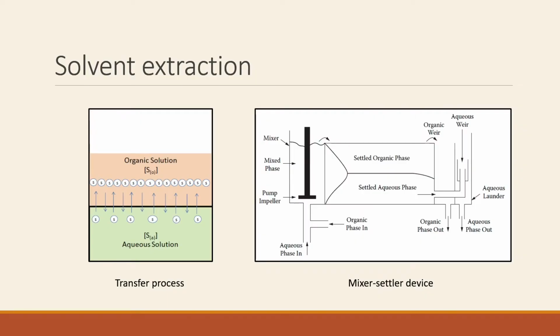Finally, the process considered corresponds to solvent extraction, which consists of the combination of two unit operations. In the first one, that is carried out in a mixer tank, the process consists in the mass transfer controlled by an ion exchange reaction of metal ions from the aqueous phase to the organic one. In the second one, the process, that in this case is physical, is the separation of both phases by gravity inside a settling tank. Since the oscillations can only have an effect on the process of the first unit operation, in this thesis the second unit operation will not be considered.